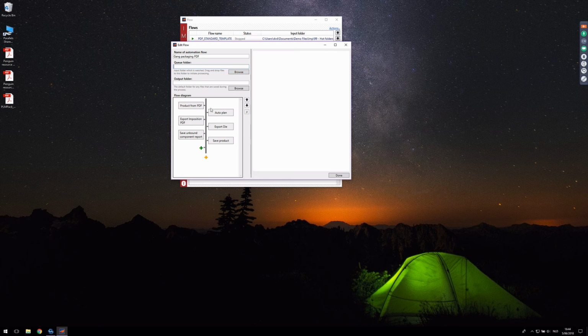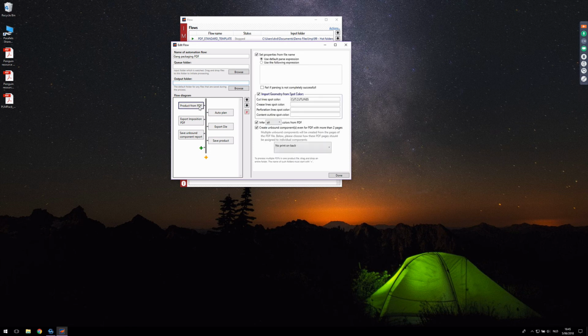And then the hot folder allows me to specify an output folder and the actions that are required for this hot folder. And these actions very closely match what we've seen in Imp in the manual version. So for example, it allows me to say, oh, I have PDF documents that I want to put in this hot folder.